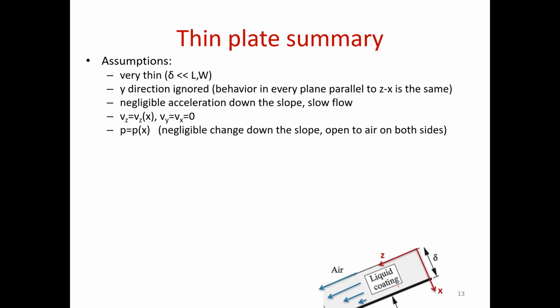So for air, it's close to zero compared to any liquid. So I have continuity across this boundary, and on the other side something with very small viscosity. And that viscosity basically makes my shear stress zero. Because I don't assume I have very large gradients in velocity in this application.